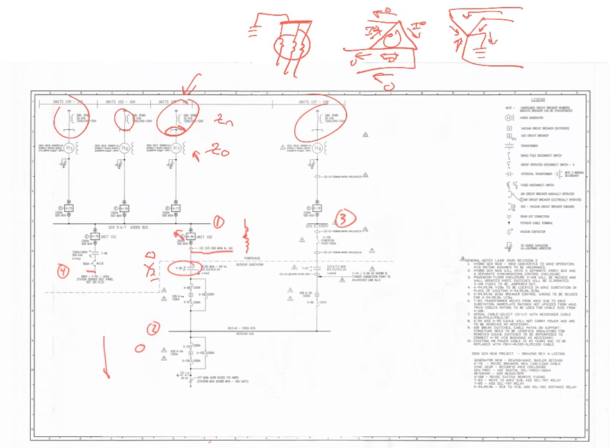So from this perspective, there is a connection here. So this is bus 1. This is bus 2. Here is my reference bus. You can see that on the Y side, which is going to be connected to bus 2, I can have 0 sequence current entering or exiting. On the bus 1 side, I can't have any current. So this is an open connection. This comes up, and this is the 0 sequence current for the transformer. So that's how that diagram is shown for that one.